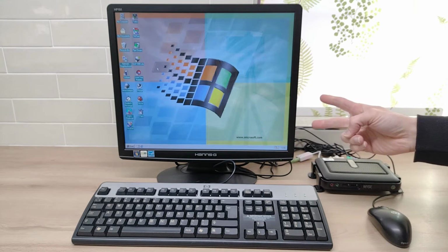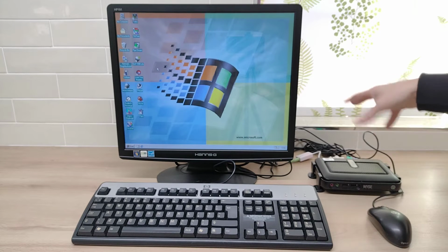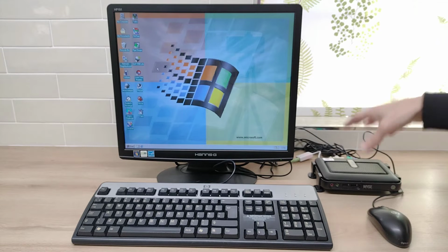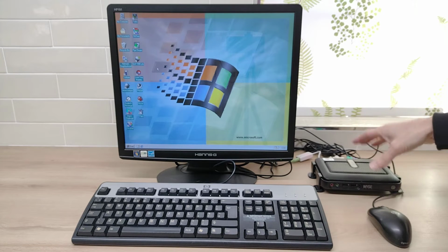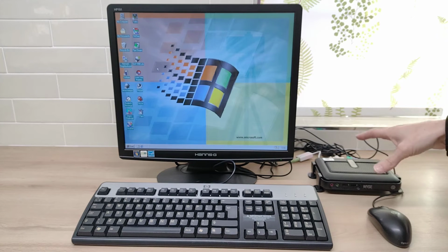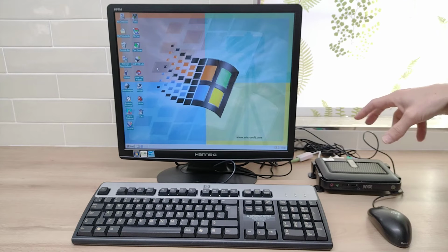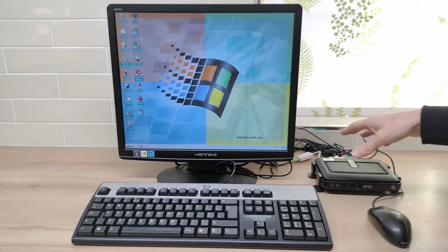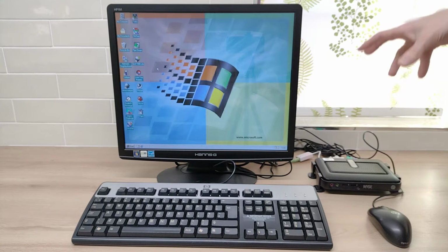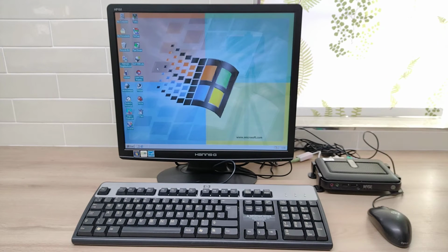The second problem that I've had has been getting the drivers, specifically the chipset drivers, to install on here. Now the VIA chipset that's in here needs the VIA 4-in-1 drivers. I think they also call them the Hyperion drivers, and they're a sort of complete package that does the chipset, does the integrated graphics, does the integrated sound, all in one driver package.